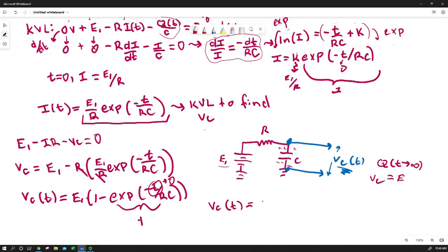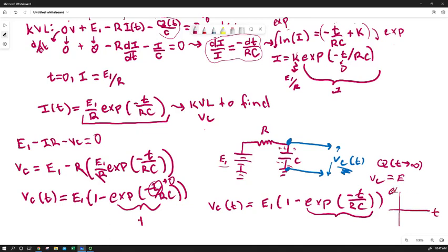We're going to use again the properties of the exponent function to do a thought experiment and check that out. So we've got negative t over RC. If t gets huge, then what we know about the exponent function is that as t gets really, really big, the exponent function of negative t on the y-axis looks like that. So the bigger t gets, with a negative sign, the more this whole term will approach 0.